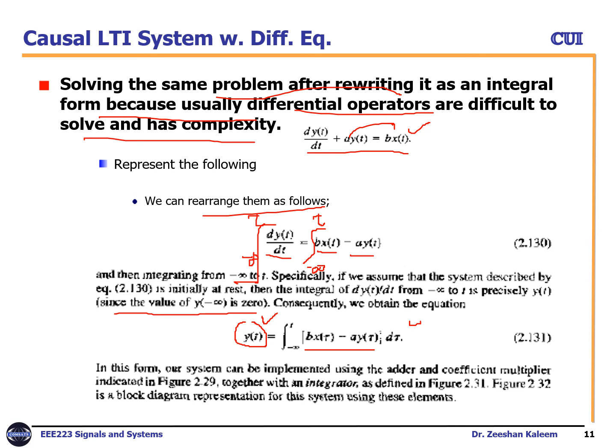In this form, you can see that it can be implemented using the adder, because the subtraction sign can be handled by the adder, the coefficient multiplier, as we already discussed, together with the integrator. So we need the additional term, which is the integrator.